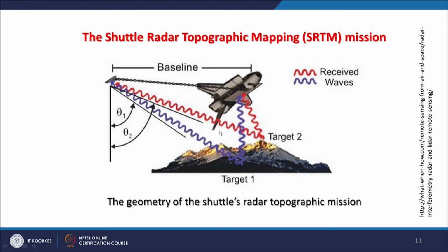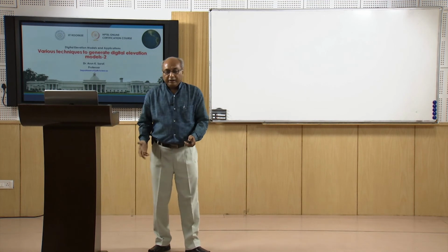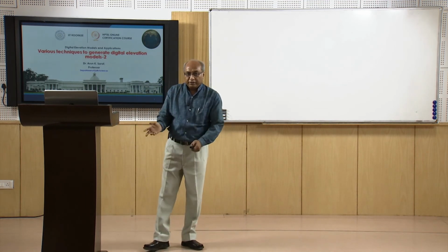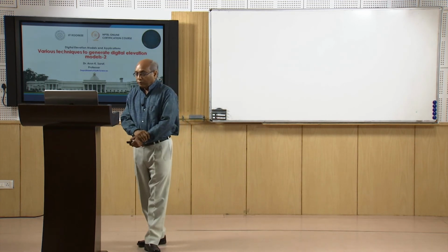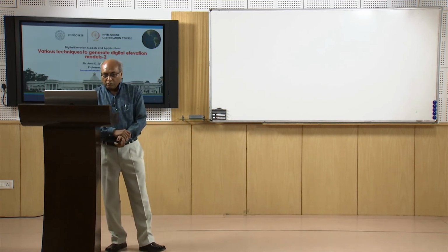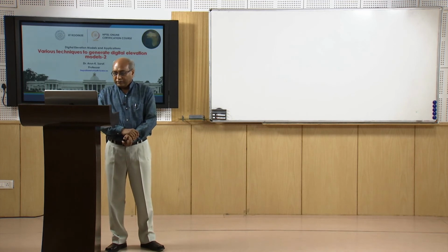This mission lasted about 10 days, and 80% of the globe was covered with data from two different angles, theta 1 and theta 2. This was processed through photogrammetric techniques, and digital elevation models at different resolutions, 90 meter and 30 meter, were generated for almost all parts of the globe except the polar regions.